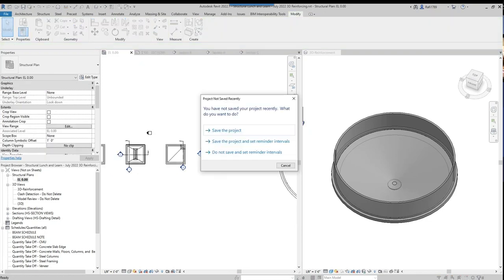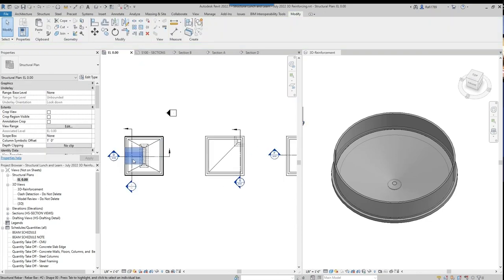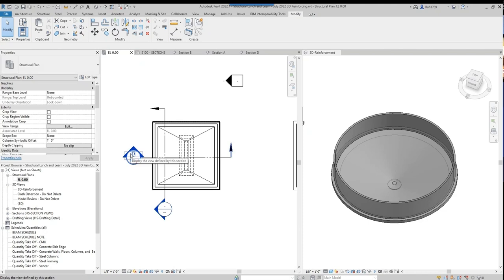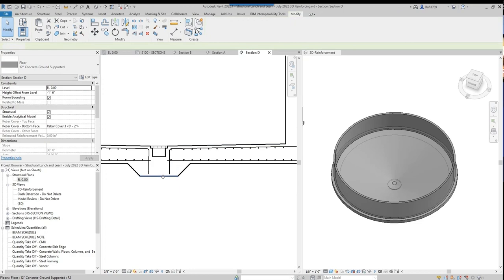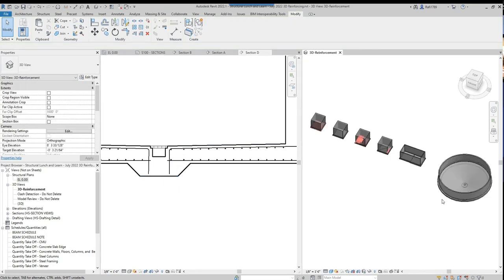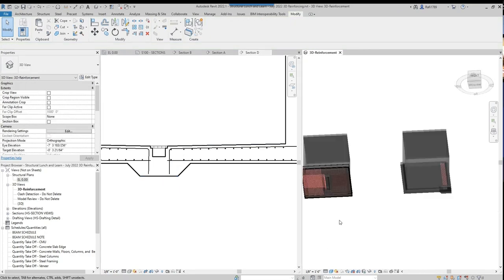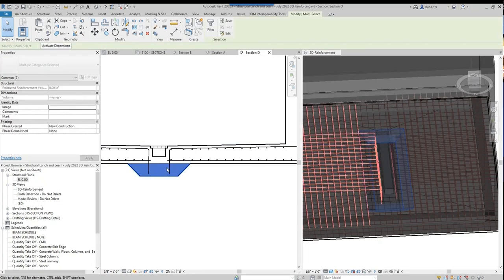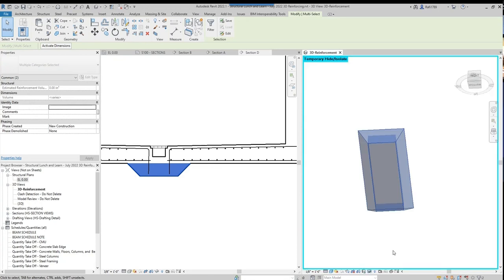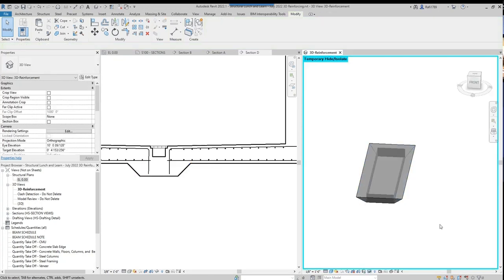All right, so let's look at turn downs or slab edges. So we have a scenario here, right? We'll continue working in this one area. Again, I'm a big fan of isolating these things. So I'll click on one, I'll click on the other, I'll hit HI, and I'm isolating it. I don't want to fight with everything that I'm seeing when I know I'm just focusing on one thing.